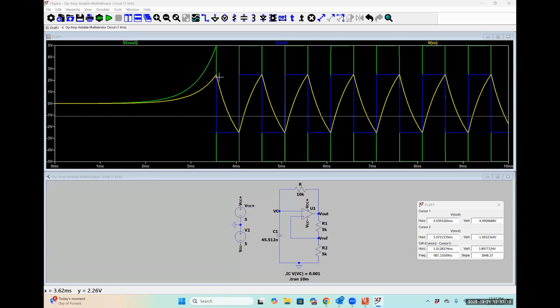We've got a positive feedback situation, so as soon as it hits and even ever so slightly exceeds it, it's going to flip the sign on that reference voltage, and then the capacitor voltage is going to slowly chase that to the next step because we know it takes time for capacitors to charge and discharge. So that's all that's going on in this circuit: the capacitor voltage is constantly chasing the reference voltage, and the reference voltage is set by whatever Vout is, either VCC plus or VCC minus applied across that simple voltage divider network.